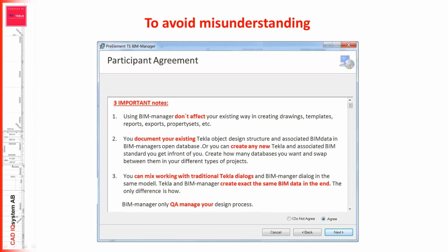To avoid misunderstanding, using BIMmanager doesn't affect your existing way of creating drawings, templates, reports, exports, property sets, etc. You document your existing Tekla object design structure and associated BIM data in BIMmanager's open database. Or you can create any new Tekla and associated BIM standard you have in front of you. Create as many databases as you want and swap between them in your different types of projects.